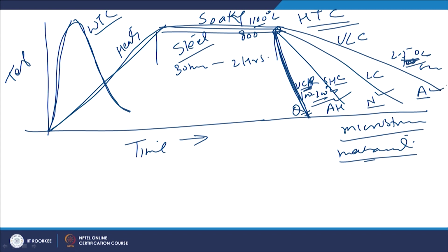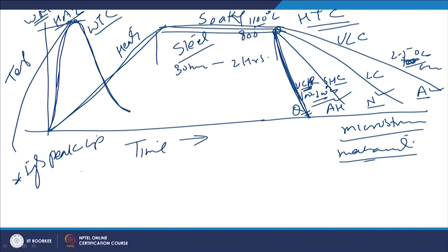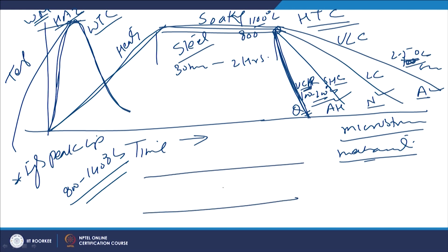So, on the other hand, weld thermal cycle, if we see weld thermal cycle of the heat affected zone or of the weld metal region, it experiences the higher peak temperature, which is of importance, like say 800 to almost up to the melting point, say in case of steel 1400 degrees centigrade. So, this temperature will be changing.